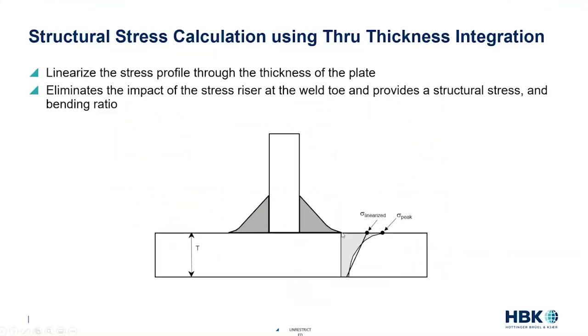We find a location where we're going to calculate a stress, and we have a path down through a particular part. DesignLife walks through the mesh along that path and calculates the actual stresses in those elements at those locations. So it's walked down through here. It doesn't have to be a path of nodes or a uniform path of elements. It's just an arbitrary mesh, but we calculate the stresses along this path. Once we have the actual stress for that path, we linearize it. So now what we have is a stress measure at our toe without the toe being there. This would be the nominal stress.